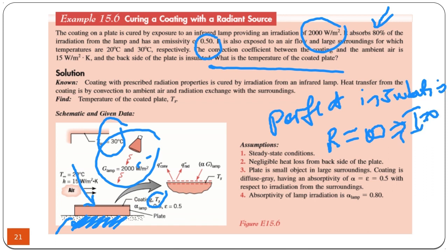This is why you wear protective gloves when you work with electricity, because their resistance is infinite. So even though you touch a live section of the circuit, 200 volts, 400 volts, whatever, you don't get an electric shock because there is no current passing through your body because of the high resistance of this glove.